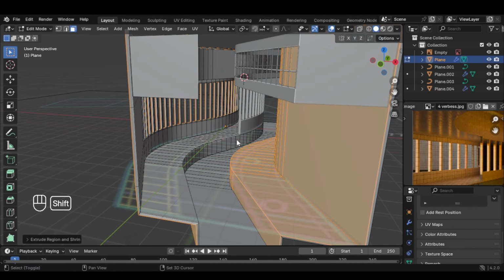And we also have to move this building, so let's select our balconies and the building. So let's go to 7, edit mode, and press 1, and let's select these edges here and just move it to about here, to this line, and also just rotate it.